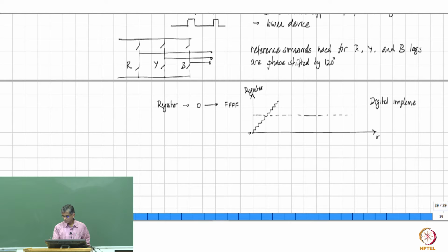No, if you look at the induced EMF inside the machine, that is going to be alternating, right? It will go high, and it will reach back 0, then it will go negative, go to negative maximum, and then come back. So that voltage waveform is going to be alternating, and therefore you have to give an input voltage to the motor that is also alternating. It has to go negative. Okay. Now it has to go negative,